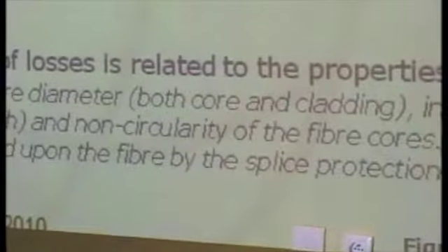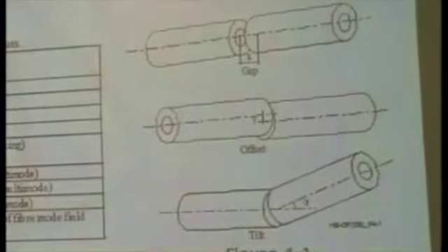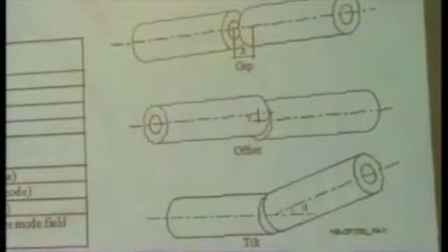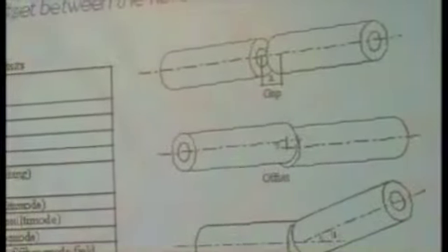It's a practical way to do it in the field. If there are a lot of bad results, maybe it's necessary to adjust the machine and find a better position. Sometimes it's better to stop and do some maintenance on the machine. If there are a lot of good splices and just some are not so good, maybe that fiber is not good for this.